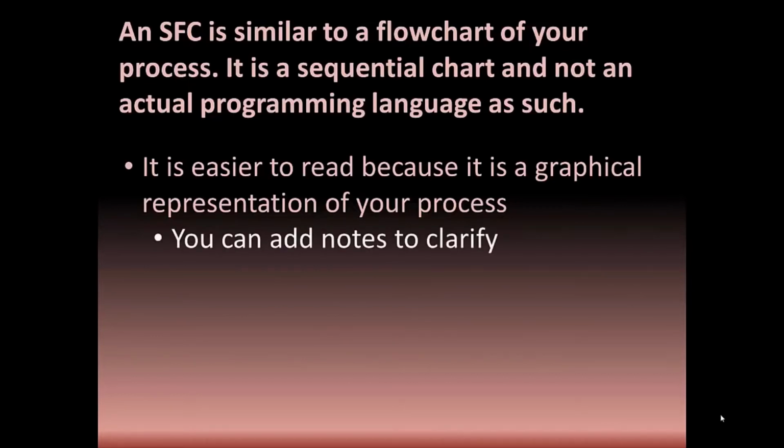Another reason that sequential function charts are easier to read, easier to understand your process, is that you can add notes to clarify. Now remember that the SFC is visible from the controller. When you hook up your laptop 2 years later, when the project is cold, the graphical representation, the flow chart with notes, is still there for you to look at.